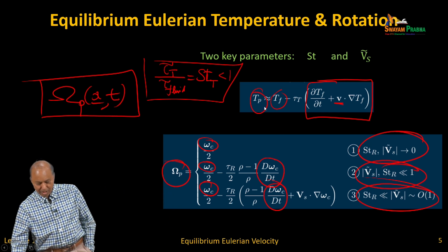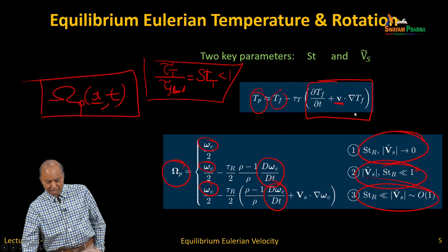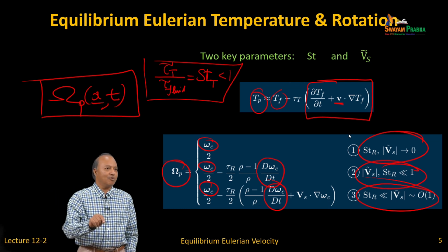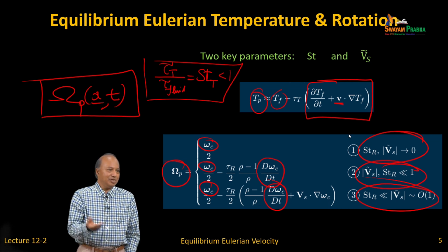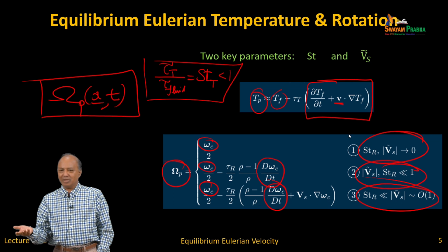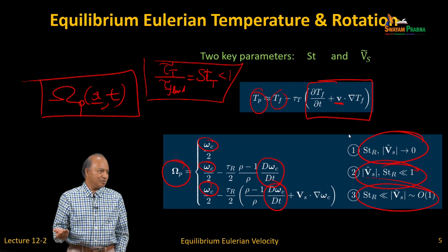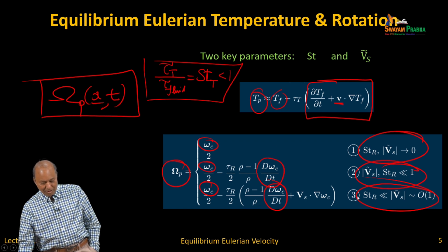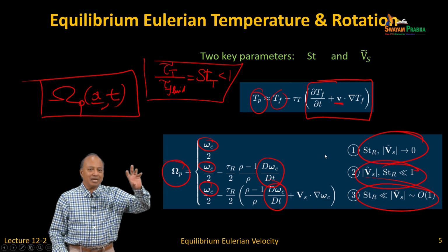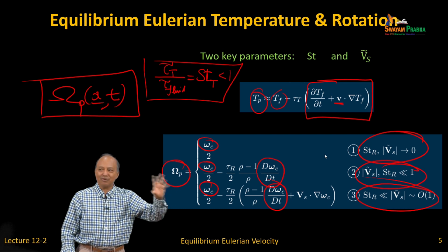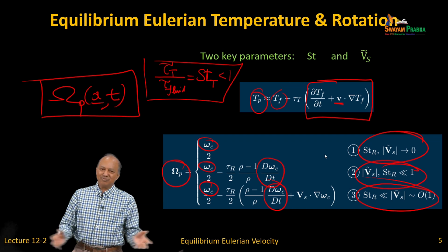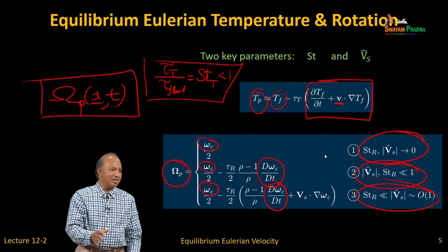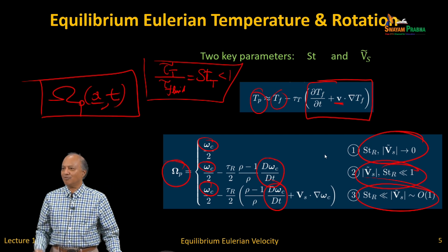temperature. You can say the particle temperature is explicitly given in terms of the local fluid temperature and the local fluid temperature gradient, which is available in Euler methods, in any CFD, and you do not need to compute the particles at all. Not only this, you can get the spin rates of the particle, because the particle spins only in response to the surrounding vorticity, and you can do the same analysis. Essentially everything pertaining to the particles you can get from your fluid.